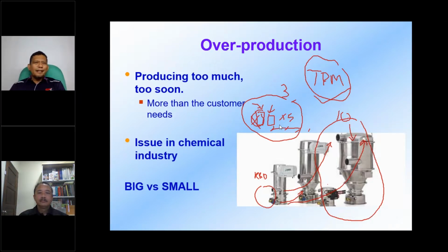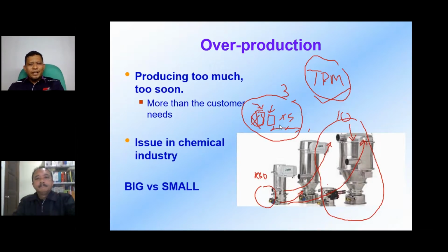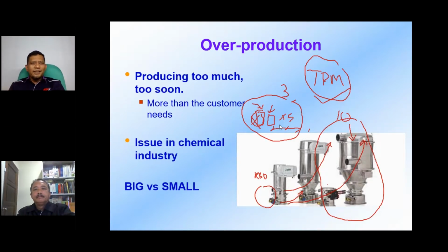Theoretically, they say if it's smaller, we can increase the pressure faster. We can increase the temperature faster. We can have a smaller agitator, the fan at the bottom or at the top. We can run at a higher RPM.